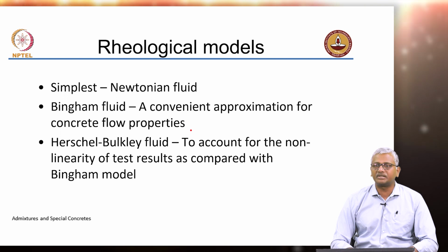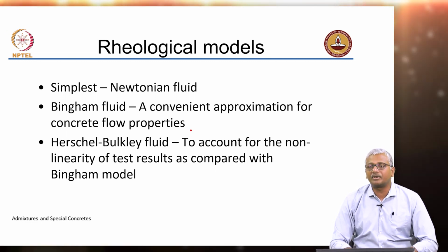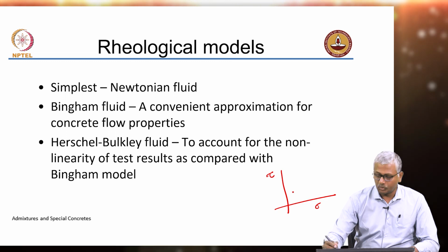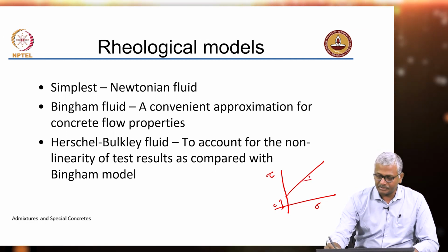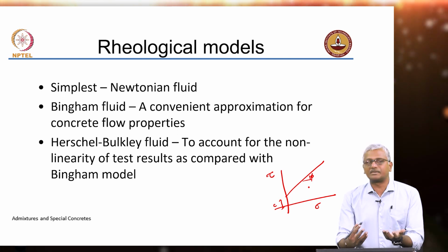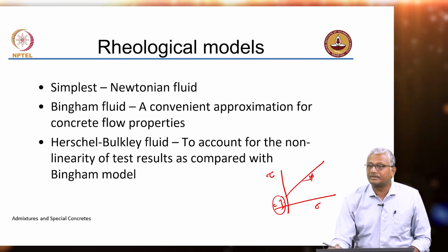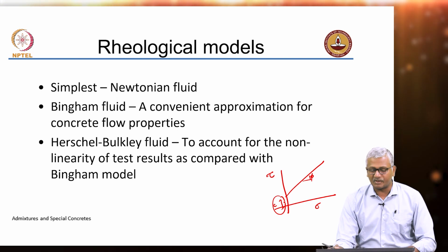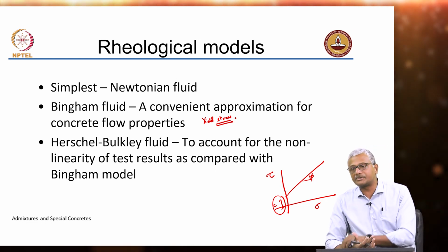In a granular material, when you draw the shear and normal stress relationship, you get a line which is straight passing through 0. But when you plot the same for a cohesive material like clay, what happens? You get a cohesion, right? C plus sigma tan phi. This is your angle phi. C plus sigma tan phi. That's the behavior exhibited by clays. So more or less similar to that is what you're seeing with materials that exhibit an initial yield stress. So this cohesive strength in the case of clays is similar to yield strength or yield stress in the case of fluids that exhibit this kind of behavior. That's why we say yield stress is the parameter, or minimum amount of stress, that needs to be overcome to cause the material to start flowing, right?